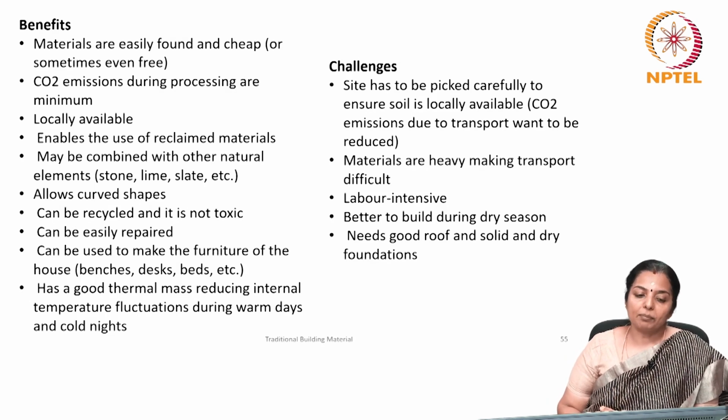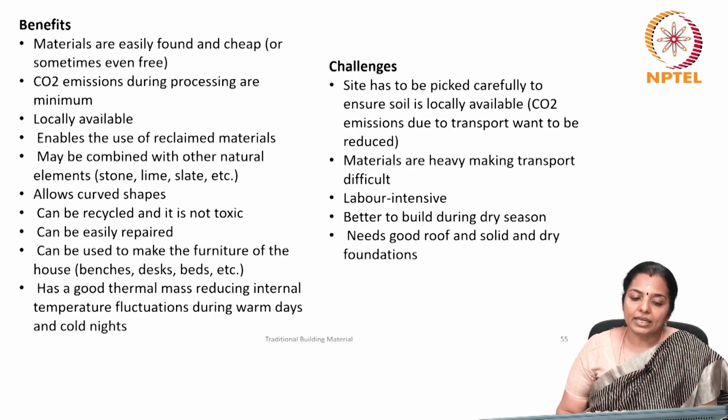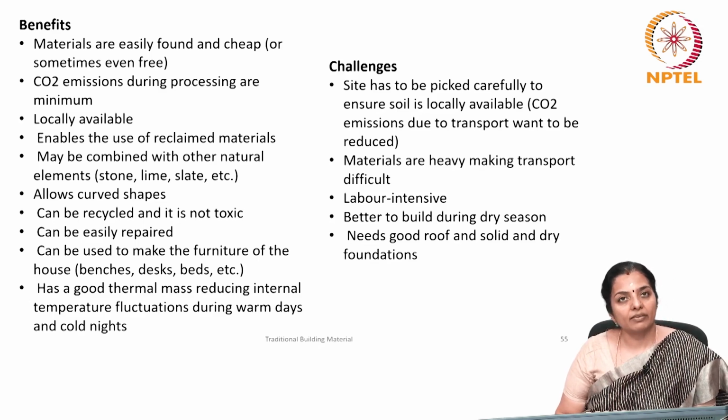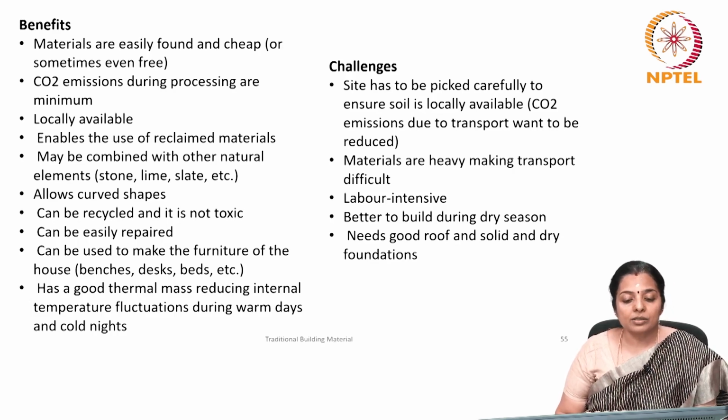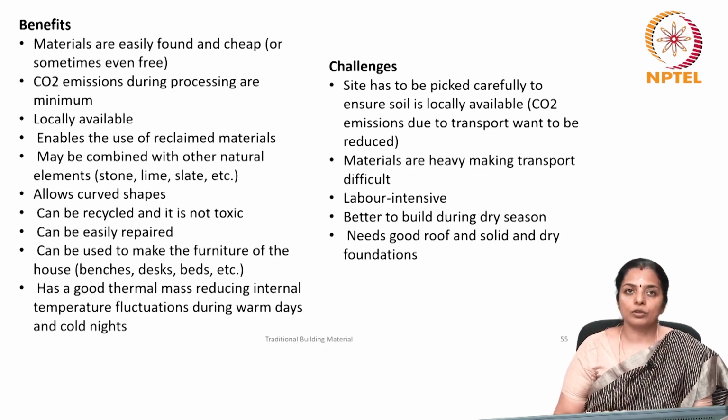Let us quickly look at the benefits. The benefits include: these are materials that are easily found and available, cheap, which means inexpensive, sometimes even free from your own site. Their CO2 emissions during processing are very minimal. These are locally available. It enables the use of reclaimed materials. They can be combined with other natural elements also, such as lime. You can get organic shapes of buildings also.